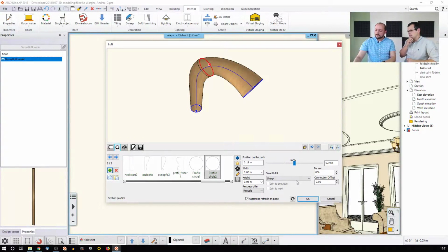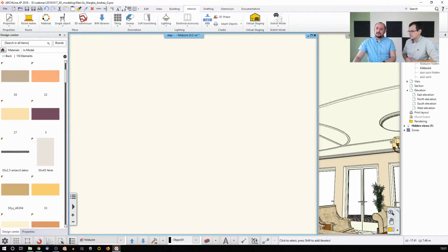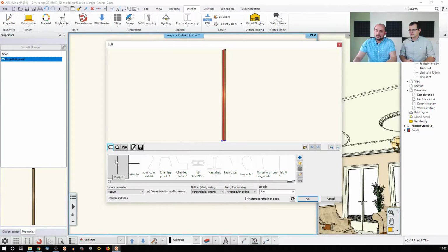You mentioned another example, and that would be based on another 2-dimensional drawing, right? Yeah, sometimes you can see those decorative items all around in case of furniture or in case of elevations, which is kind of this twisted shape moving around. This looks like a rope or something like that, and then it goes like this. You just use the sweep tool, Loft tool. And then I'm just using the same vertical item now.